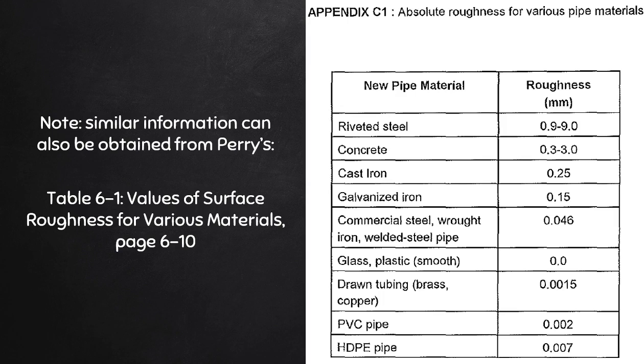Sometimes we would also want to line our pipes with glass, for example, when using highly reactive streams, or we would like to line the pipes with polytetrafluoroethylene or polyvinylidene fluoride when working with streams that contain very reactive materials like fluorides.